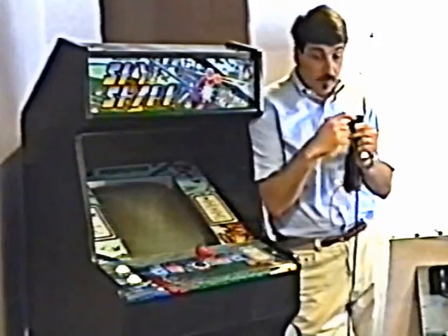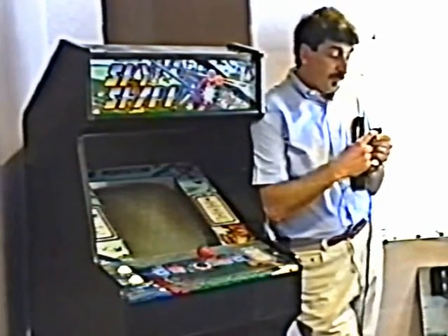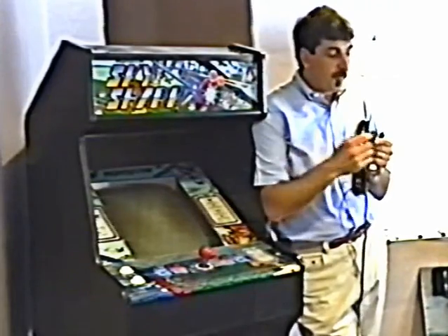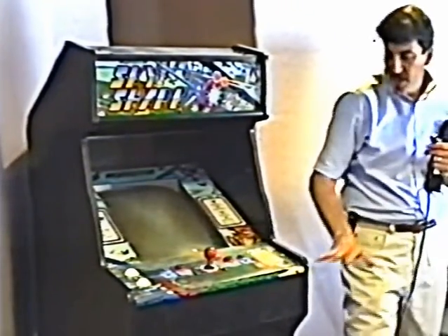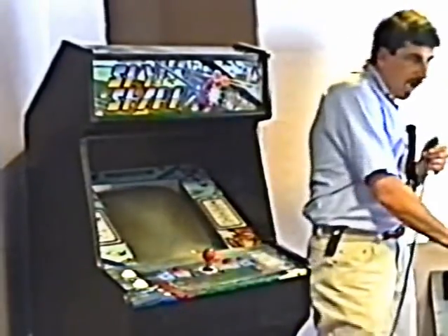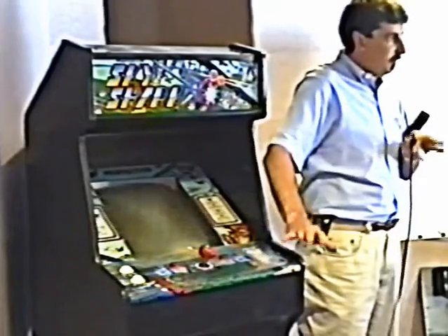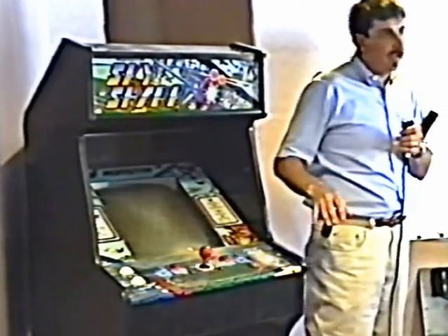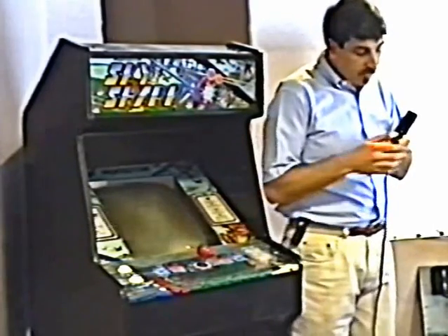Number one, the ground pin is missing here, which usually doesn't cause major problems, but if the ground pin is missing, you have a possible shock hazard between this game and another game. You've probably seen this on pinball machines. You touch two rails of adjacent pinball machines, wow, you get a little buzz off of that. If they're both properly grounded, that's impossible.